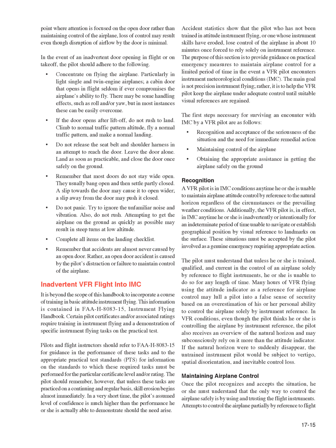A slip towards the door may cause it to open wider, a slip away from the door may push it closed. Do not panic. Try to ignore the unfamiliar noise and vibration. Also, do not rush. Attempting to get the airplane on the ground as quickly as possible may result in steep turns at low altitude. Complete all items on the landing checklist. Remember that accidents are almost never caused by an open door. Rather, an open door accident is caused by the pilot's distraction or failure to maintain control of the airplane.